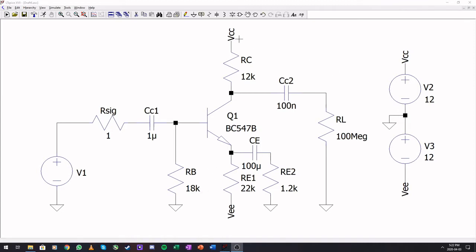Okay, here I used some of the tags that I mentioned earlier, or the nodes that you can label, and I set up the power supply to be a dual power supply. This is how you set up a dual power supply in Spice, and you can put this anywhere in your schematic, away from the rest of the things, so it's not so cluttered. So these nodes VCC are connected and that VEE is connected.